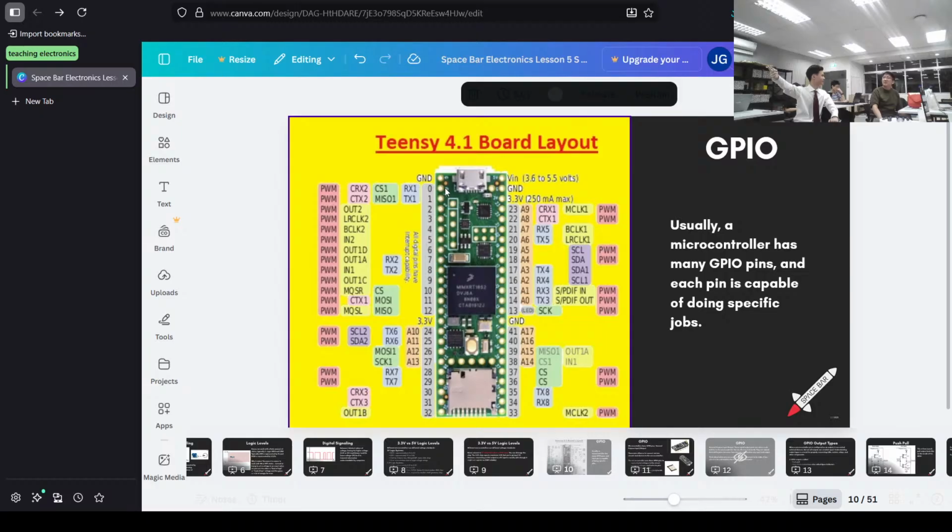In most microcontrollers, TX and RX are dedicated pins on the board. If I want TX and RX, it has to be wired to that pin. On ESP32, I don't care. I wire it to whichever pin is free, and I tell the software, this pin is TX now, this pin is RX now, and internally with magic, it will connect the chip inside to the external pin. So it can reconnect its own pins internally. That's why it's a mux, a multiplexer. That is actually what it means.